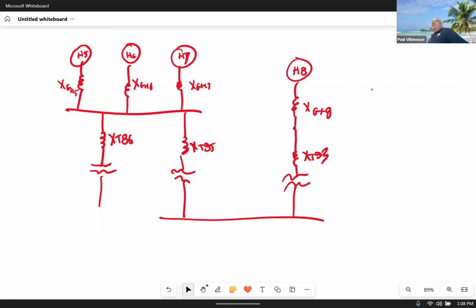It's a gas, SF6. And then you can get any voltage you want. So all the higher voltages go with sulfur hexafluoride. But it wasn't that long ago, they used to use oil, because oil actually is a pretty good insulator. So they would use oil breakers. And even before that, they actually had air breakers. They just had huge breakers for 345. They had these massive arc chutes, big concrete things, so that they could blow arcs in them. It took a lot of space and a lot of effort, but that's what they used to do.